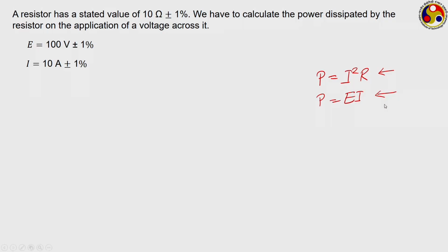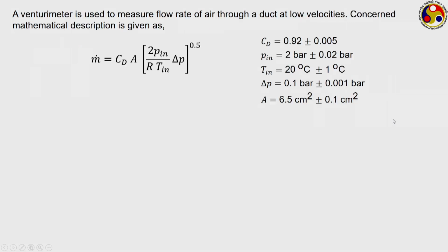In this case, if their uncertainties are different, you may get an idea about which process to follow. After getting your answer, I can proceed with this. Same in this problem, try to see the product of sensitivity and uncertainty for each of the components and compare those values to see which one has the largest contribution in the overall uncertainty.